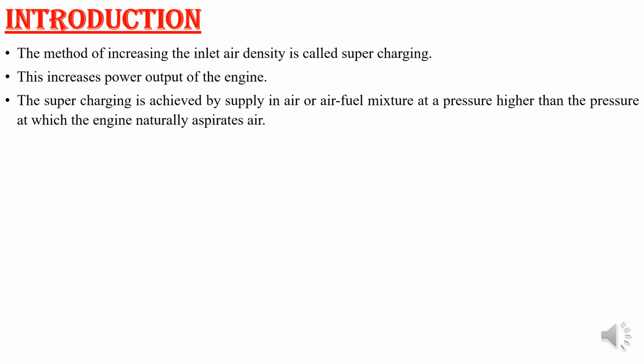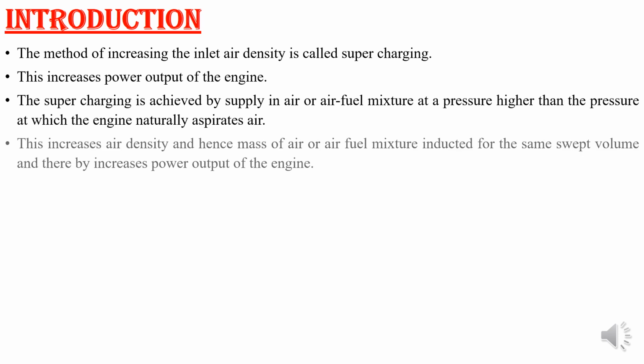While increasing the air density, the mass of air for the same swept volume will increase, thereby increasing the power output of the engine. So while increasing the air density, your volumetric efficiency is going to increase. More air will be introduced inside the cylinder, hence the power output can be increased.